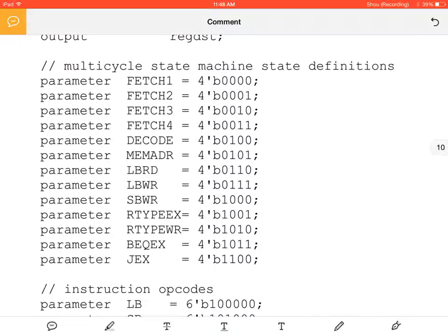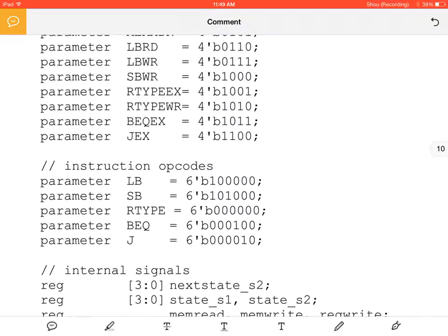Parameter addI, and you could say parameter addI. I would add, just for the time being, addI = 4'b1101; right? And the reason I'm just going to say addI is because I want you to add. The next thing you're going to do is add the instruction opcode. From section 8, which is where I presented it, what's the specific instruction opcode for addI?